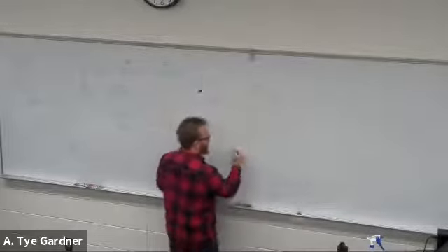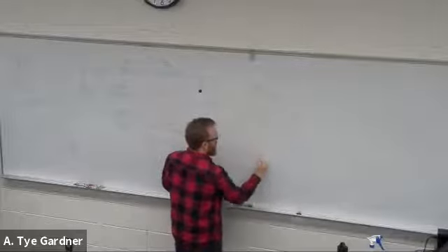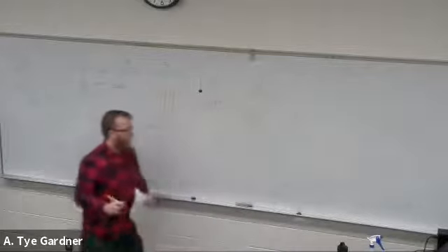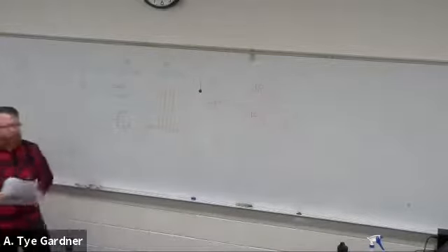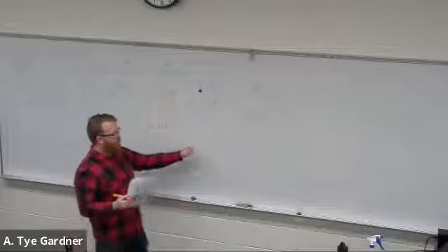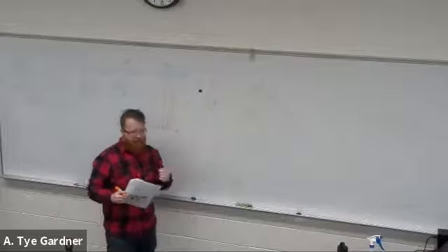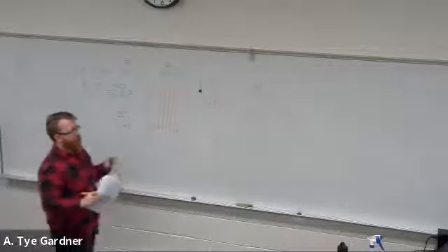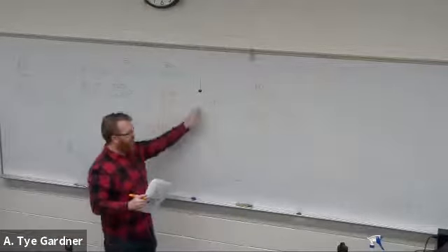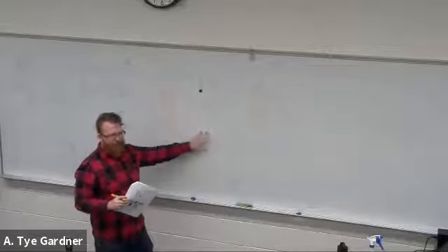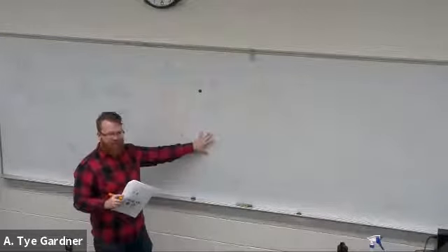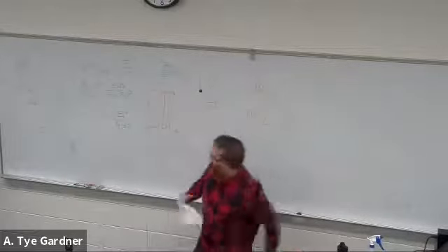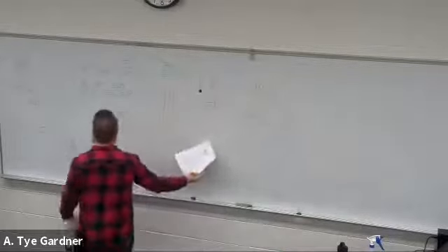Well, G looks too much like grams, doesn't it? Okay, because I can't draw in italics. Gauge factor times epsilon. So what they're describing here, what they're interested in is the delta R by R. Now, unfortunately for us, if you go look at some of the books, they will interchangeably refer to the gauge factor and delta R by R as sensitivity. They use them as an interchangeable term and it drives me crazy, but this is not the sensitivity.